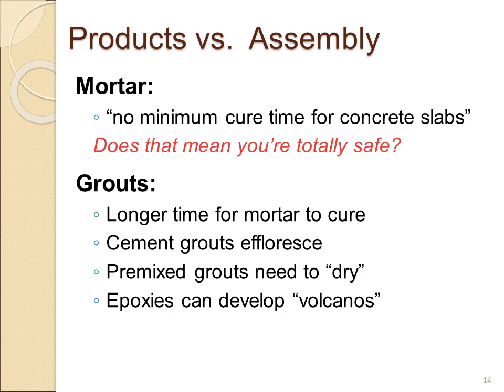You may also experience efflorescence coming through capillaries or pinholes or little areas on the edges of your tile with all of these grouts, and that would definitely affect the entire assembly. So considering whether there's moisture in the slab or in the substrate, it makes a big difference as to whether we're going to be successful or not.